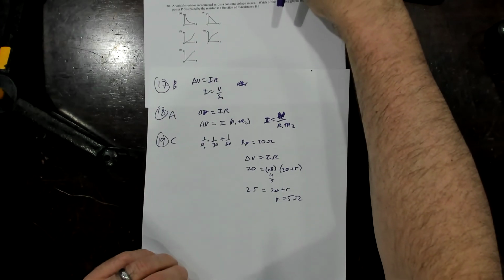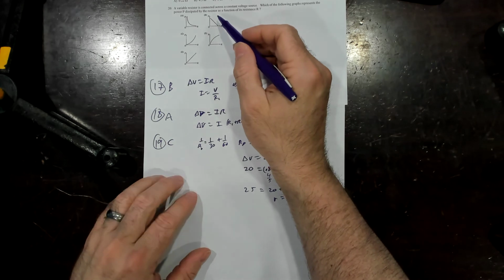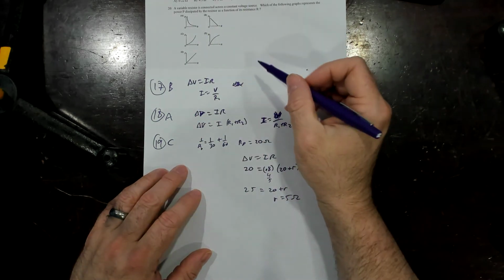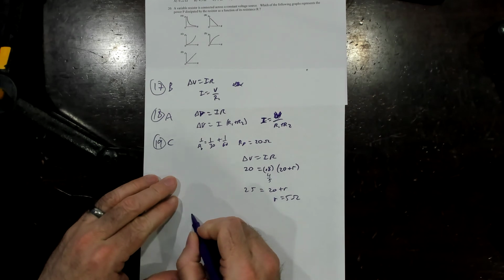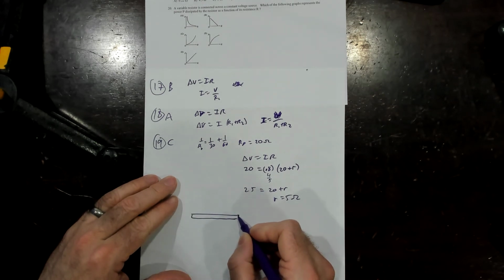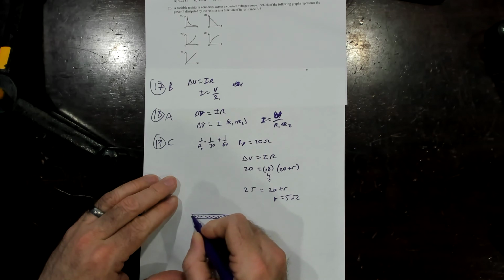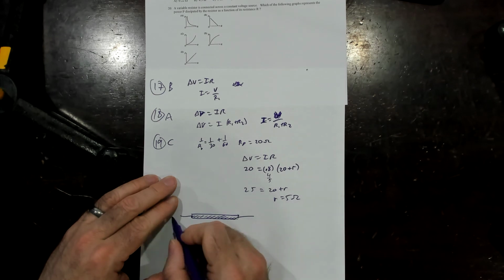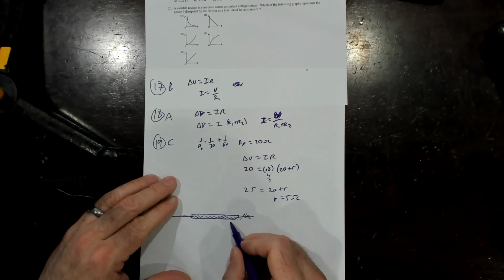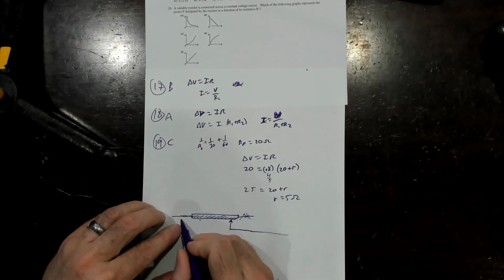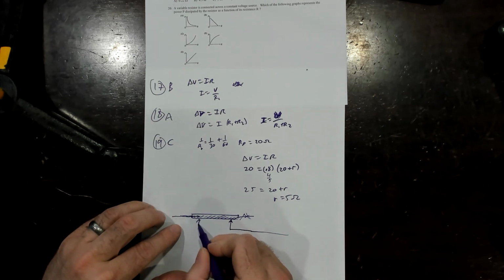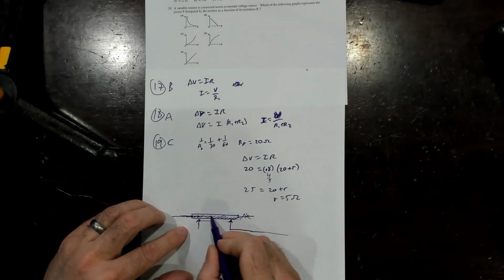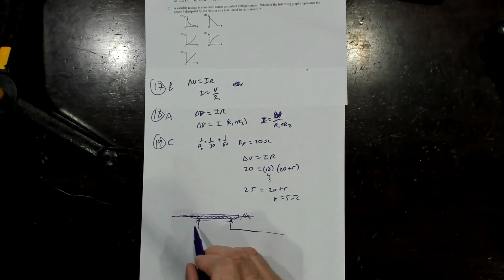Okay. And last question. Variable resistor. So it's a resistor you can change the resistance of. You can imagine, for example, having some long, thick wire made of some material that's a conductor, but kind of a bad conductor, and charges have to burn off a lot of energy to wiggle through it. Well, imagine I have my circuit hooked up here, but instead I have a little connector here to go to the rest of the circuit, and I can slide this. So if I slide this down, the current doesn't have to go through as much of this junk, and so there's less resistance. I slide the connector into here, now it's got to flow through all this to get to there. I've increased the resistance. It's a variable resistor.